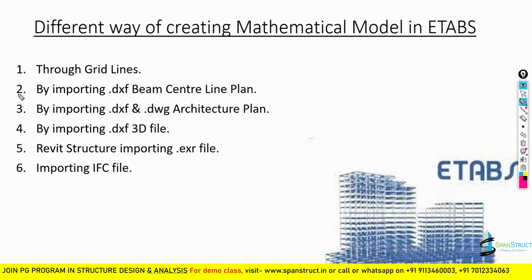Now let us look at the second method, importing .dxf beam centerline plan. Now this is a very important method, and in the maximum number of projects you will be using this method only. Now in this method, what is happening here is that we are going to create a beam center line. As you know, we get the architectural plan from the client, then this architectural plan has to be converted into a structural frame plan, and after creating the structural frame plan, the beam center line has to be made.